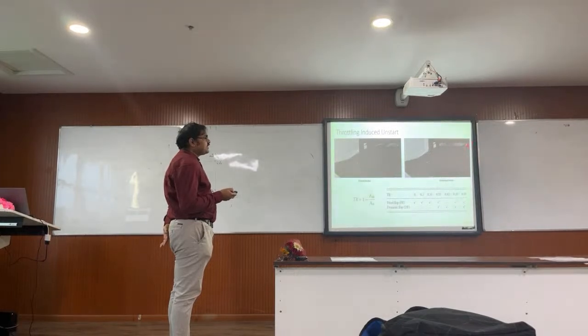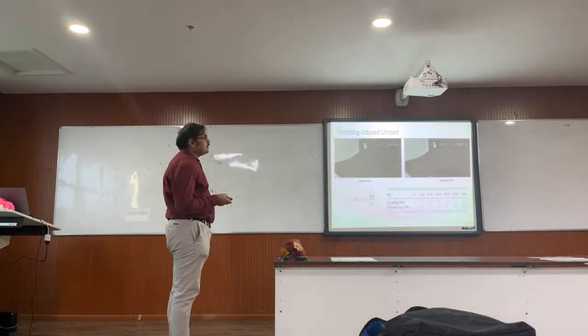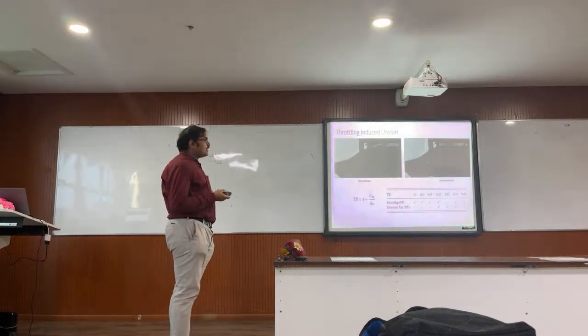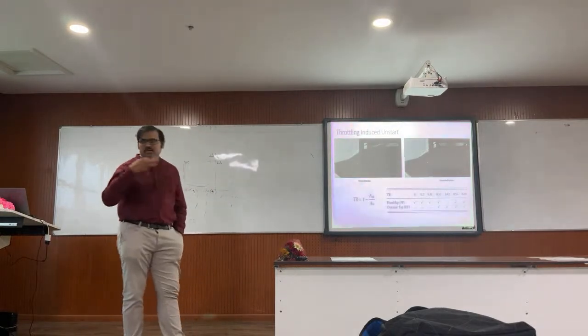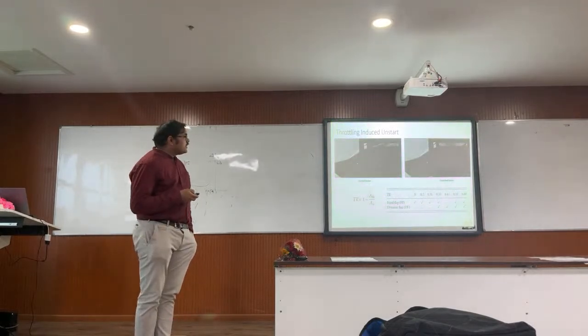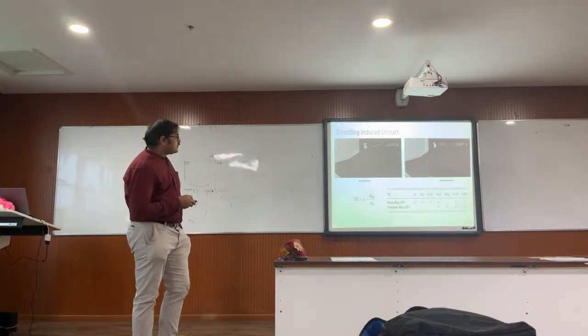Okay, but you can see this here. We have raised the flap over here in order to increase the back pressure and provide a kind of throttling to the flow. Once this is done, the shock has been pushed to one stop. And here, from the back, it comes out, and then it follows a very large amplitude of oscillation, where it goes out, then it comes in, and goes out, and comes in. It is extremely large amplitude. Okay. So this is an unstarted intake.